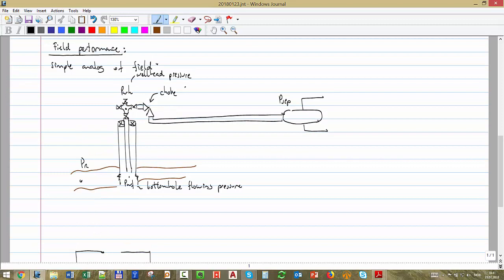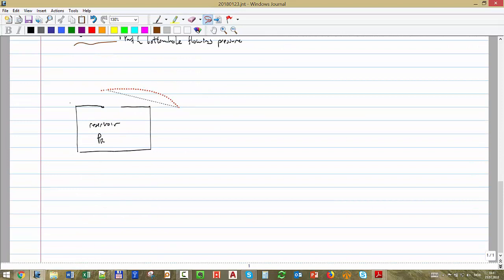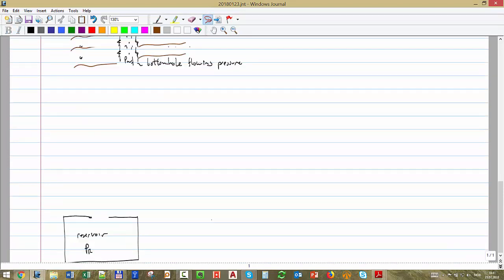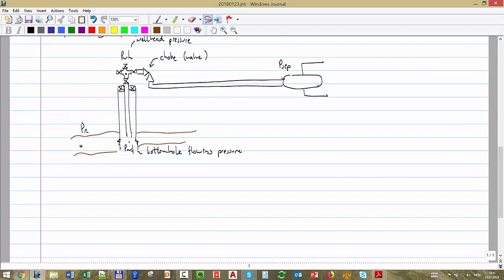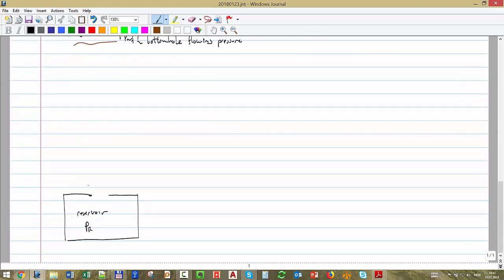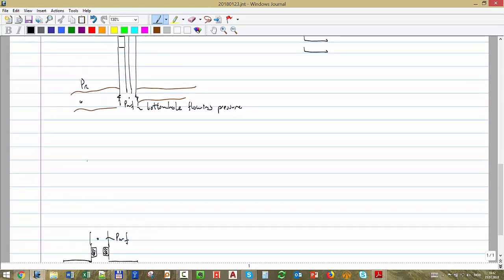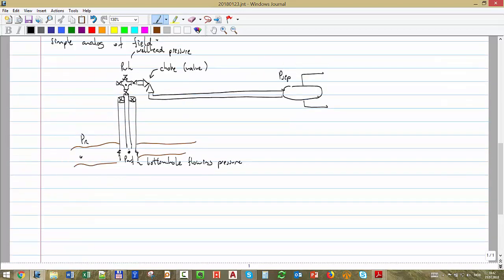It's like a valve, like the one you have in your house. So if you think about the system, to come from here to here, I will have a pressure drop, right? And that pressure drop we petroleum engineers normally call drawdown, right? But in my analog, I say, well, that's a tank, and I'm going to put here a restriction. Okay, from reservoir pressure is like a place where I have a restriction that I have to flow through to PWF.